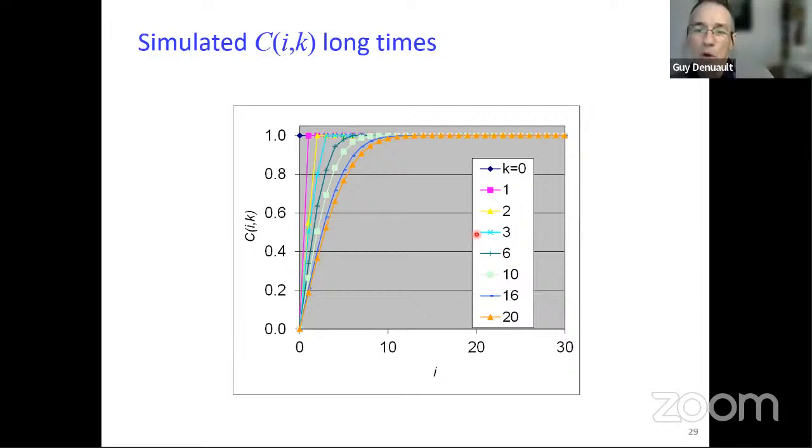This is now over a long period of time, and I've gone up to K equals 20. What I want to show you here is that when you look at the shape of the concentration profile, it's quite jagged at the beginning. But as you iterate longer and longer, you find that the concentration profile looks rather smooth. So for this pale green here, for 10 iterations already, my concentration profile is very smooth. That means that the numerical scheme took about 10 iterations to converge. And by convergence, here I'm just looking at the shape of the concentration profile. Now, from the analytical solution, I know this is the complementary error function, and I know it's got this sort of rounded shape. So I can tell that my scheme here only took about 10 iterations to compute the correct concentration profile.